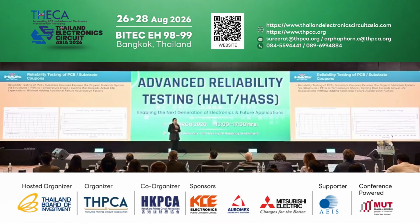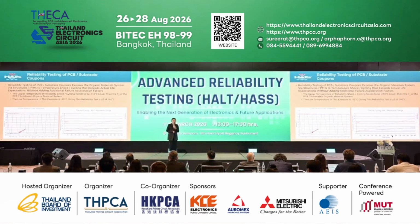Another thing we want to talk about is reliability testing of PCB and substrate. The reliability testing of PCB and substrate exposes organic material systems, via structures and PTH to temperature shock or cycling that exceeds the actual life expectations without adding additional failure acceleration factors.